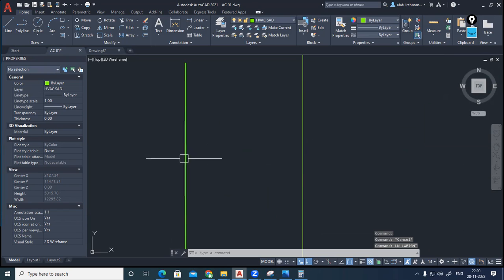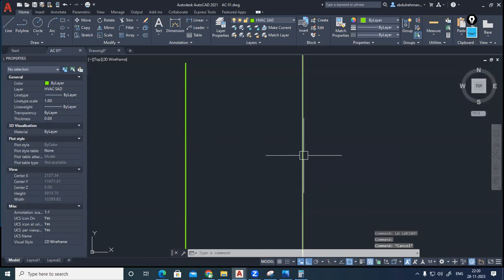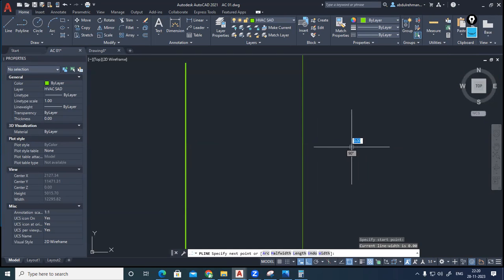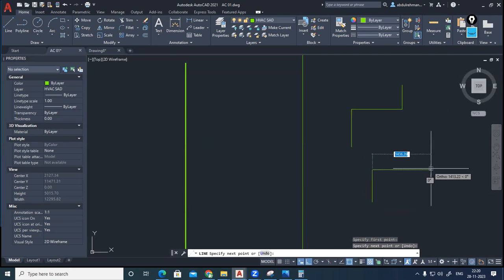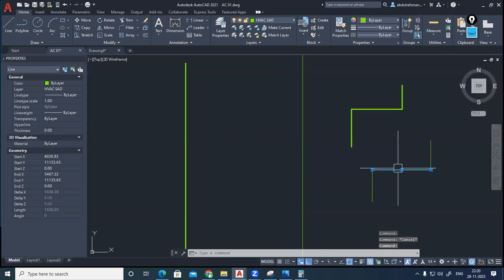Okay. So most companies, when they are making the drawing, do not go by the line weight, they provide the thickness for the services by global width only. But the global width parameter will function only for polyline, not for line. Line, it is not there. Correct. For example, I'm selecting a polyline, and at the same time, I'm selecting a line as well. Select your polyline, global width 20. Select your line, no.